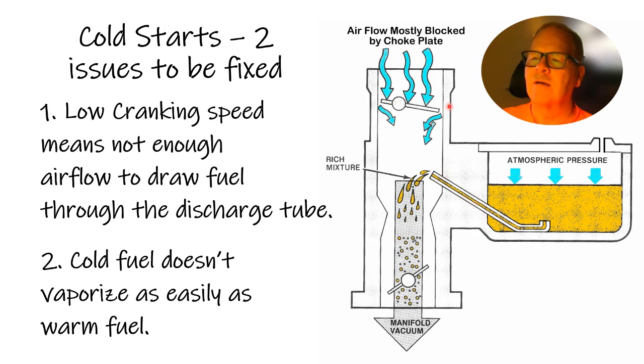Of course, the air bleed, a lot of times it gets air from way up here. It'll have holes on the top of the carburetor that you don't realize what they were there for, but there they are. And there it is, atmospheric pressure pushing on this. I got that vent there for the purpose of illustration, but remember, it usually gets that vent from a tube that's coming down from here.